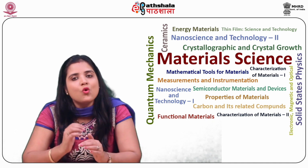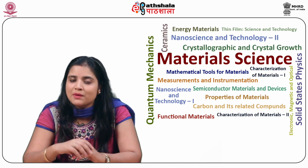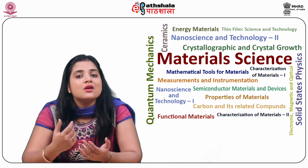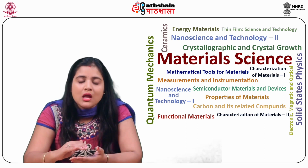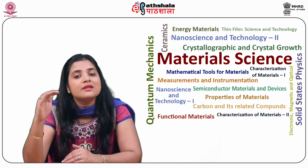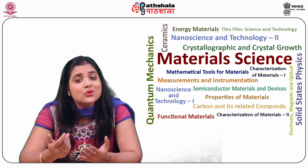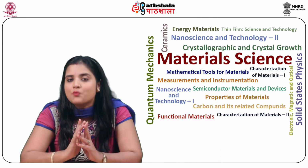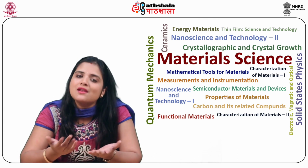Let us choose the voltage range of the analog signal to be developed to lie between 0 and plus 7 volts. Therefore, the smallest digital level, which is 000, can be thought of to be equal to 0 volt, and the largest digital level, which is 111, can be thought of to be equal to plus 7 volt. In between 000 and 111, there are 7 discrete levels to be defined. Thus, the analog signal is divided into 7 levels.